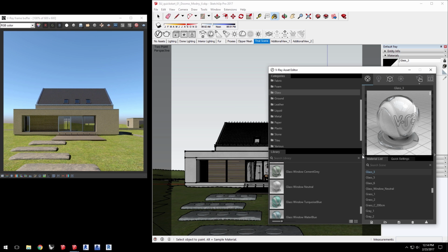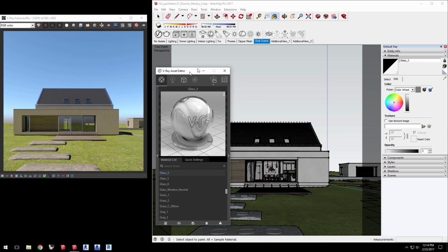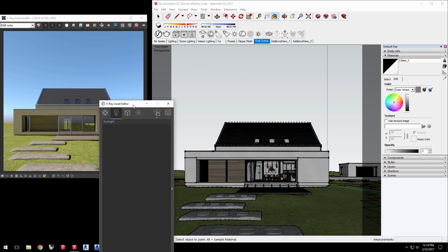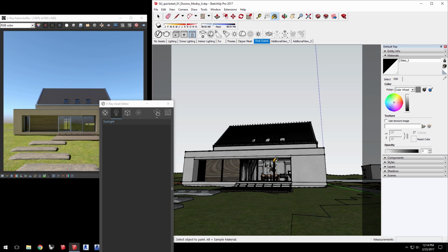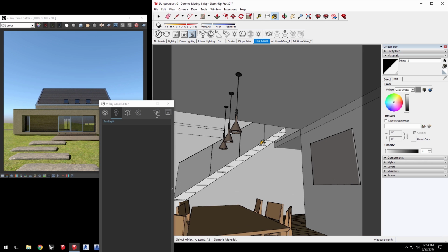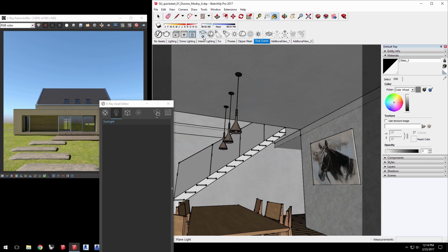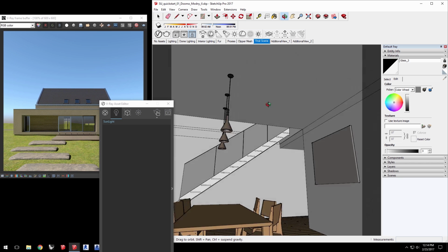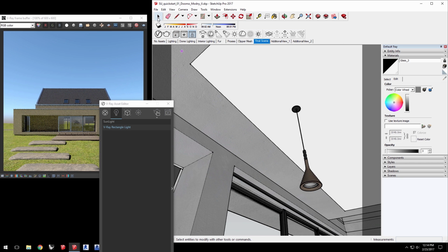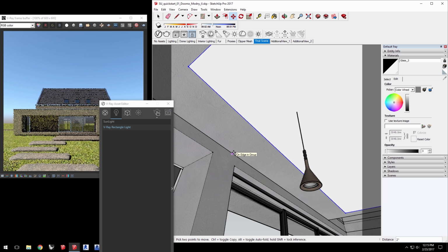Click the arrow to close the material library and switch to the Lights section. We only have sunlight, but it's easy to place new lights in the scene. Click the Lock Camera Orientation icon, and this lets us move the camera without updating the interactive rendering so we can quickly zoom inside the house. Once inside, click the Plane Light icon in the toolbar, and then go ahead and place the plane light on the ceiling like so, and then go ahead and click back to the Select tool. Make sure the light is placed just below the ceiling.